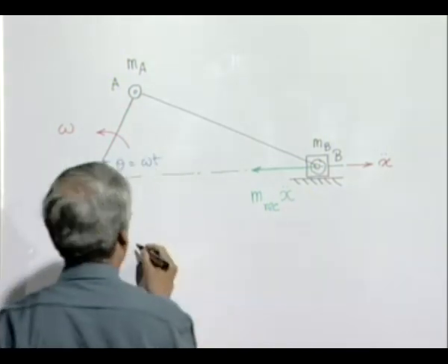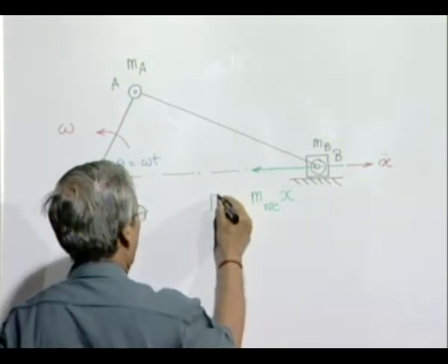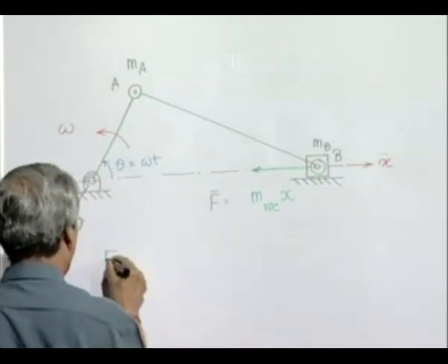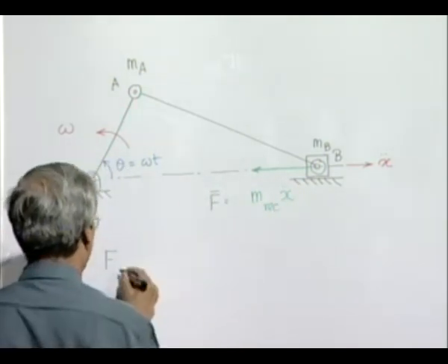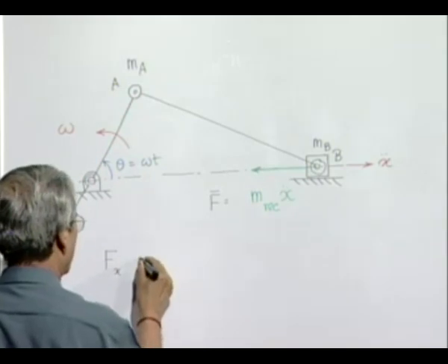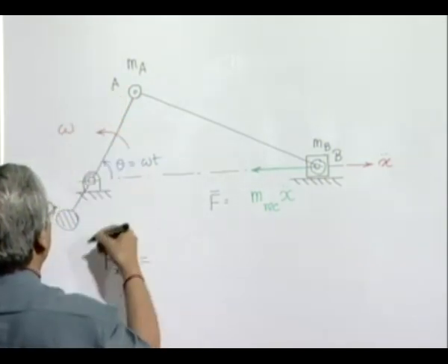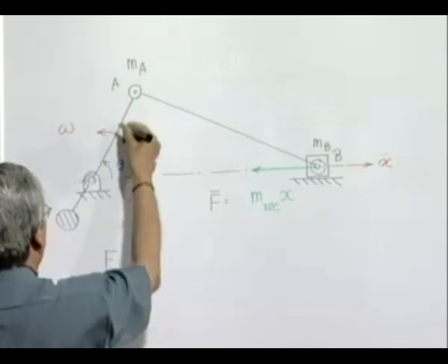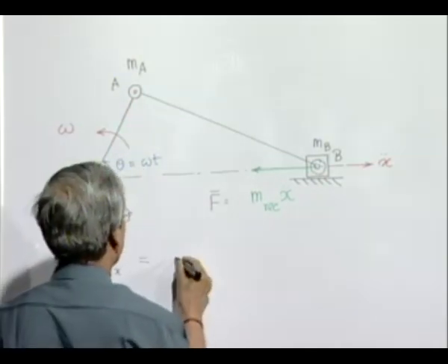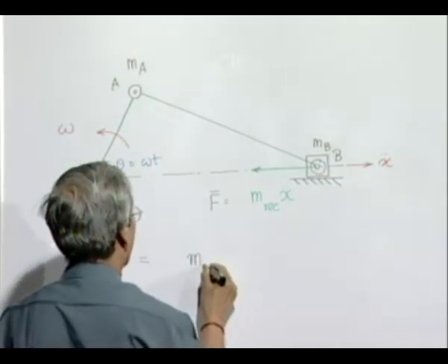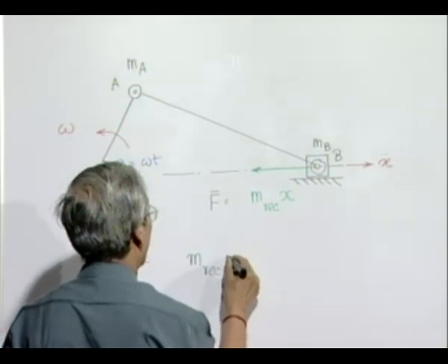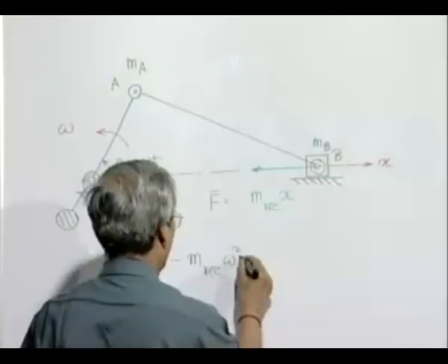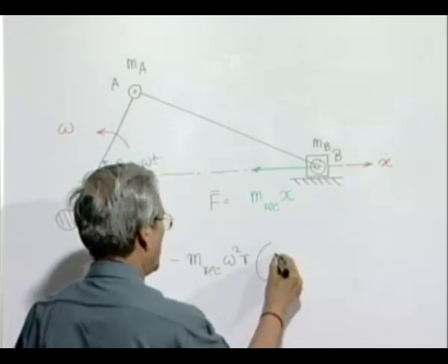We have seen that the inertia force or unbalanced force is given by only its x component. So, we call it Fx. The y direction unbalanced force because of the rotating mass has been taken care of by the counterbalance. It will have two parts.